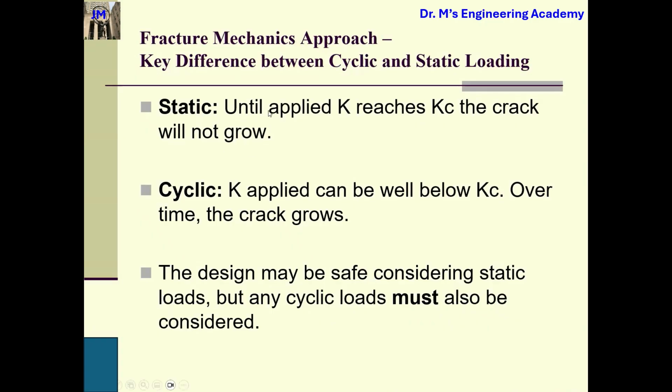So for static, we apply the stress, and based on geometry, material property, and applied load, we can get a stress intensity factor K, right? Then we compare this actual stress intensity factor K with the KC, and KC is a critical stress intensity factor, which is a mechanical property of your material. And we compare this K and this KC.